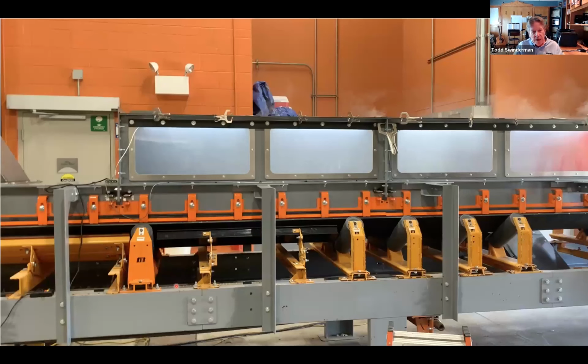So what does that look like? We've set up the test to determine if the computer calculations are correct. This is Martin's Research Center. Here you'll see their external wearliner arrangement. In this case, the skirt boards are raised up, so the material doesn't rub on the skirt boards, but the wearliner is put on the outside. This is maintenance friendly. You can change your wearliner from the outside. You can adjust your skirting from the outside.